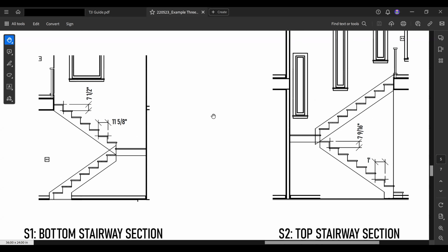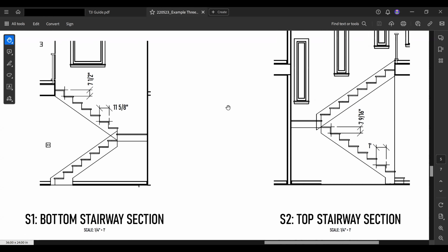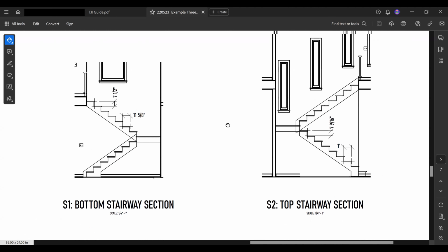It's just a general way of describing to the construction guys, hey, this is what was intended. This math ended up making the stairway this shape and this size to fit in this space. So when the carpenter is cutting out the stringers, which are the boards that are going to make the shape of the stairway, he's going to know what math to use. Oftentimes they might adjust and use their math on the spot anyway, because they want to fit it to what's been built. But this is a basic idea.